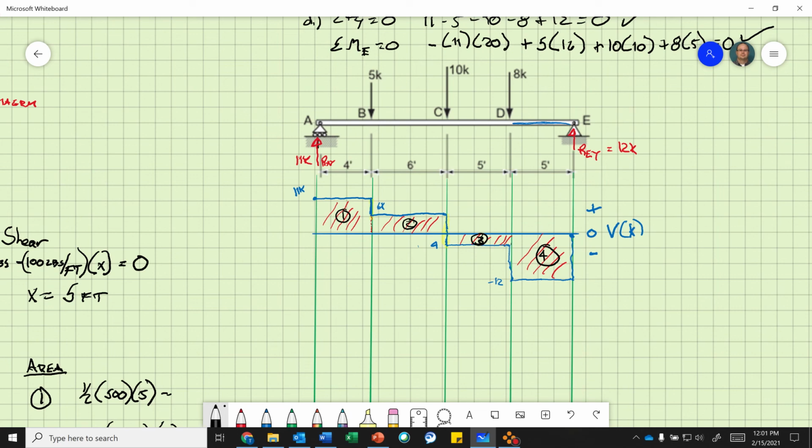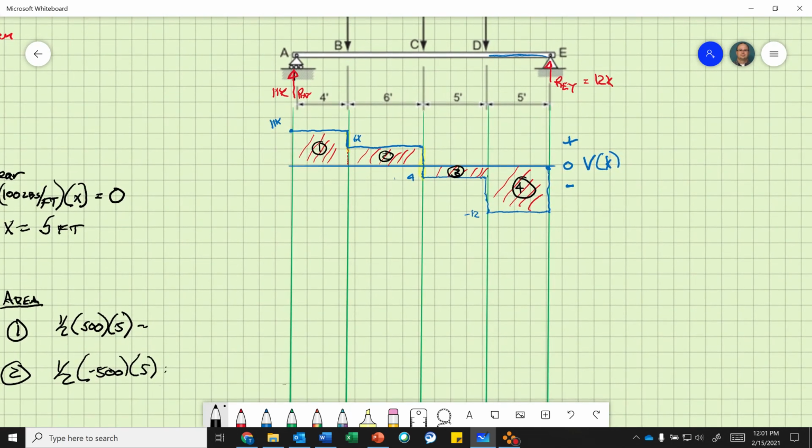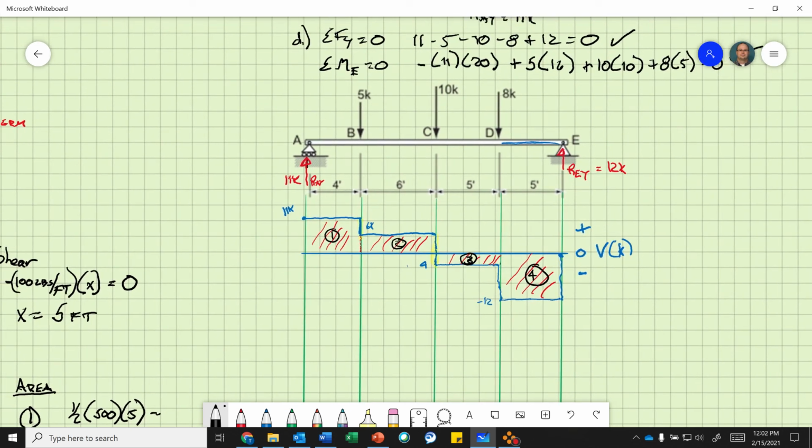Okay. Do I need to project any further points down? Any points of 0 shear? We have it. It's already at that point load, so we don't need to add a different line. Okay. So now let's calculate our areas. So we don't need to calculate the point of 0 shear. And remember, these are 0-degree curves now, each of these, and I would like you to identify those as 0-degree curves because they are rectangles.